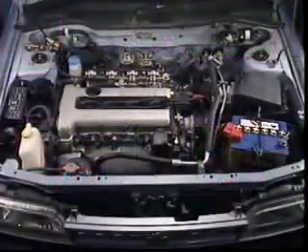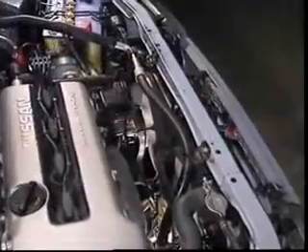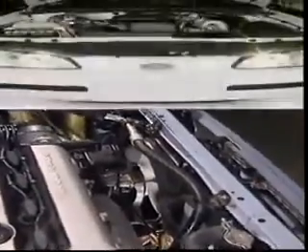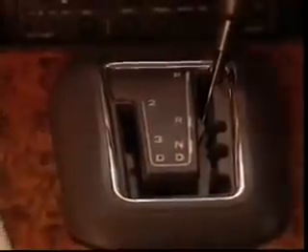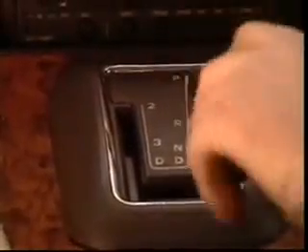Higher load can be caused by extra frictional resistance that occurs in a cold engine and by electrical loads from headlights or the cooling fan. Shifting an automatic transmission into a drive range or engaging the air conditioner compressor clutch will also cause a drop in the idle speed.